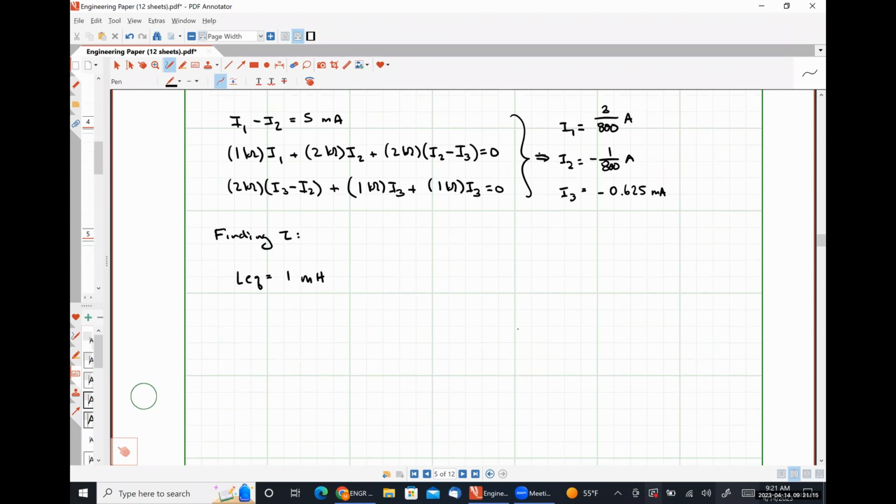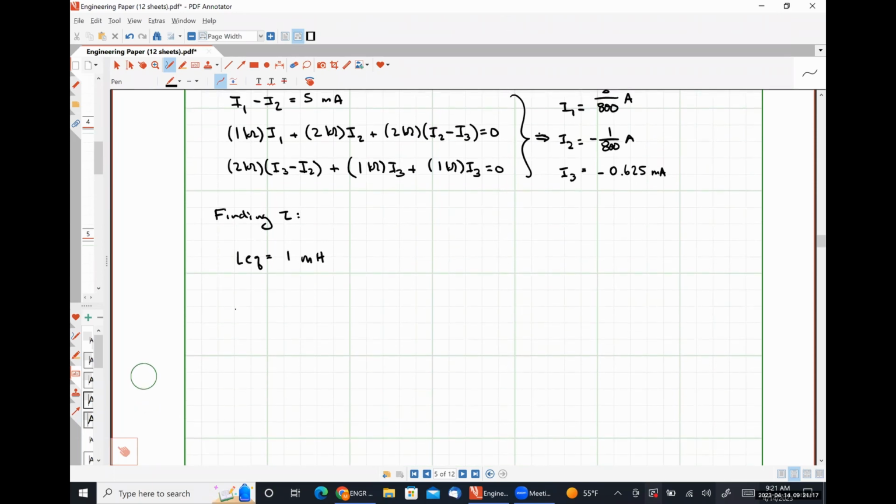So I need to be looking at a dead network. So my 5 milliamp source looks like an open circuit. Here's my 5 kilo ohm resistor. Recall, and it's very important that we're looking at this during the transient condition, which means our switch is closed down like so.